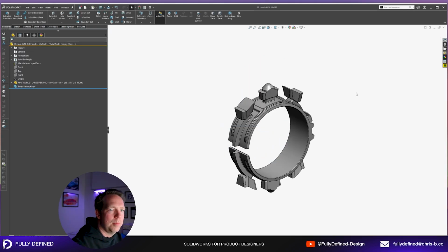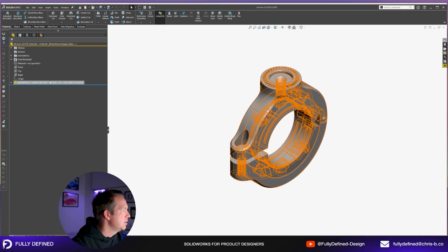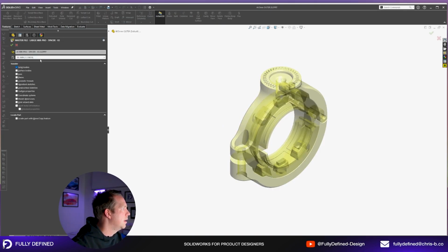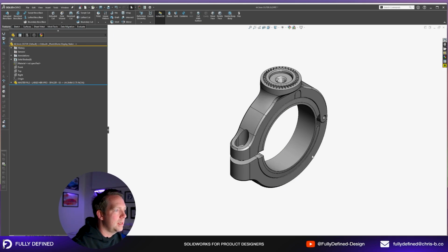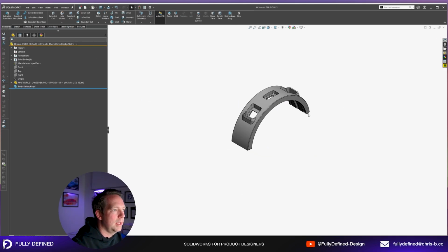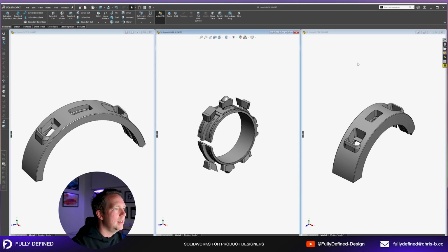And then the third part that we've saved here, 45.1mm, this is where we make a change. So I edit the feature, I change the configuration. This configuration is referencing the original master file. I press OK, and you can see the geometry is changed, and I keep the new body that I want. So now we have 3 files, our outer, inner, outer, all linked back to one master file, but each of these child parts only has the single body, which is what we need for our suppliers.